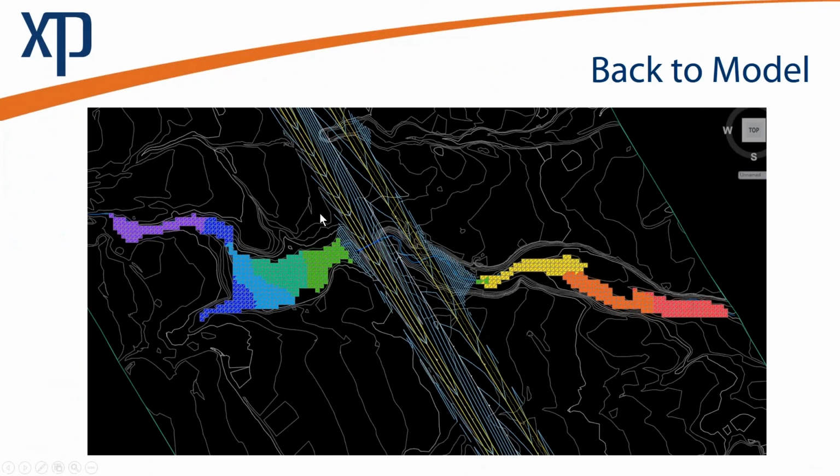And when I get back into Civil 3D, for example, I can create a digital elevation or a surface from a DEM file, and I can select that ASC file. And what that'll do is import all of the squares, subdivide each of those squares into triangles, and we can look at that directly on top of our existing ground surface. And now that's a 3D surface that can be used in cross sections, could be used in profiles, could be used for earthwork calculations or things like that. Maybe you have to prove fill or something like that. Cutting compensatory, occasionally you'll have to do compensatory storage calculations, and this would provide that scenario to do that.